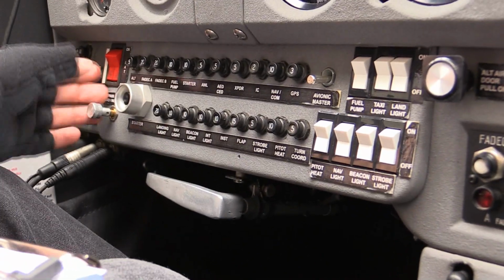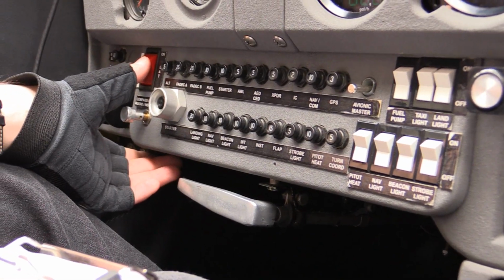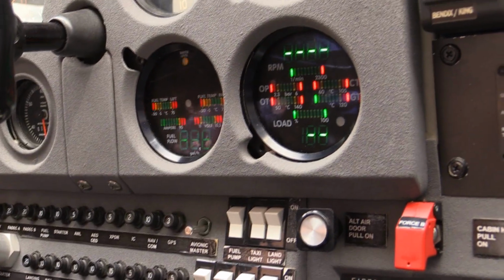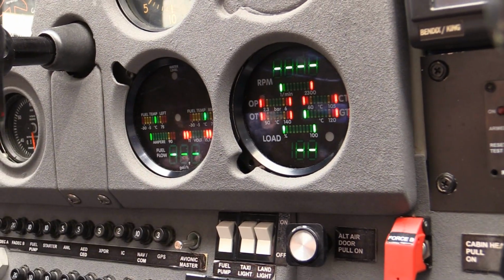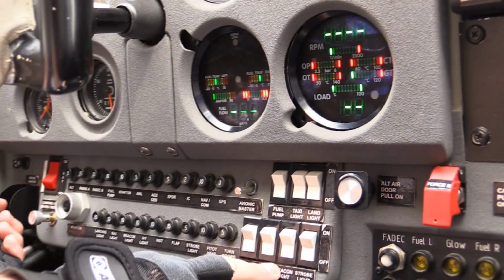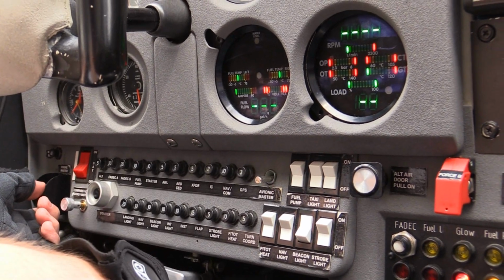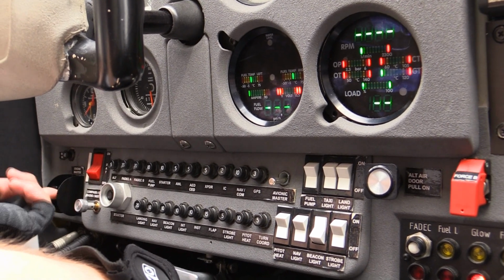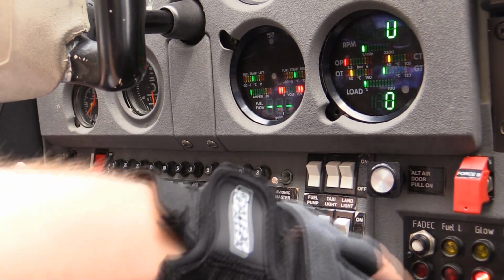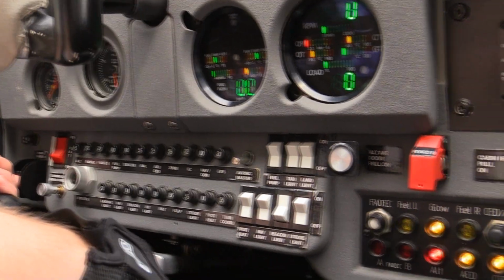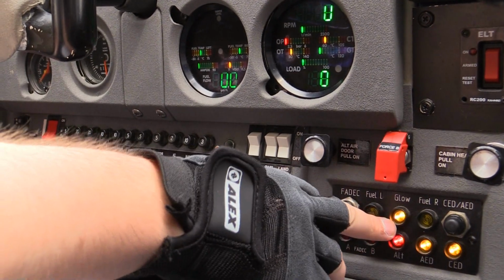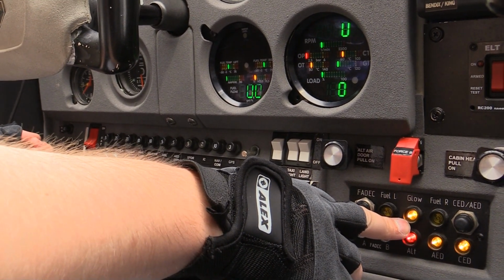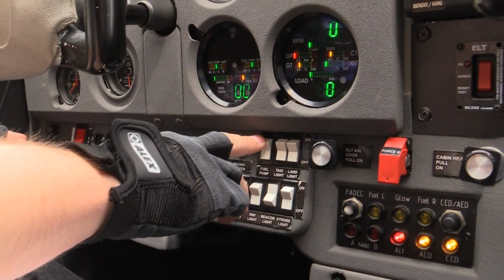Now let's turn on the aircraft. First we engage the battery and main bus switch. And now you see the FADEC of this engine coming to life. And next we activate the beacon. So now we have the flashing beacon on. Everybody knows we're going to start up soon. And now it's the engine master to on. This will actually arm or activate the FADEC. And now you see it glowing. It's a diesel engine. So we have to wait until the glow light is extinguished. Thereafter we turn on the fuel pumps.